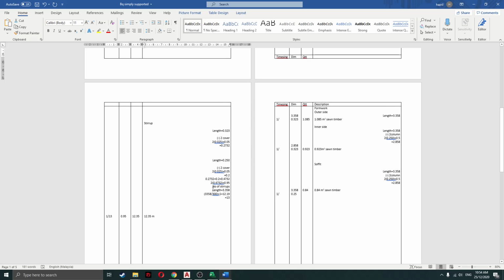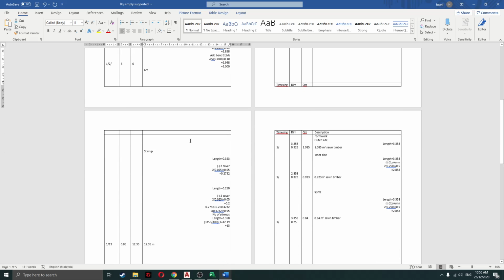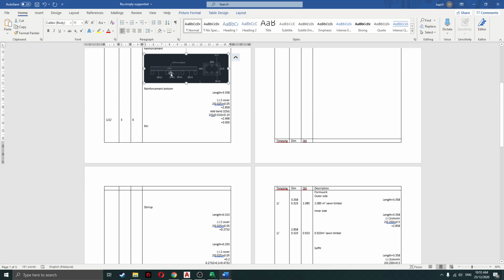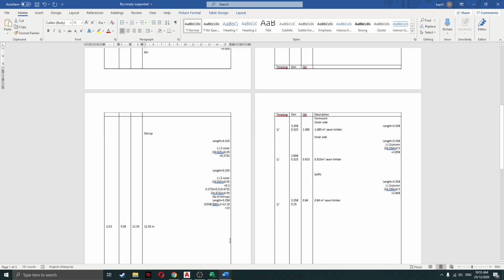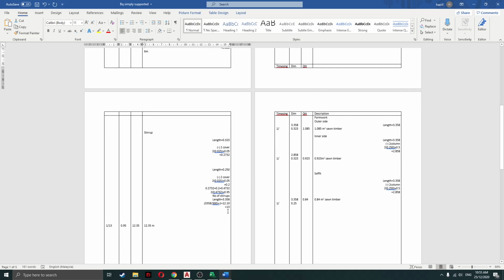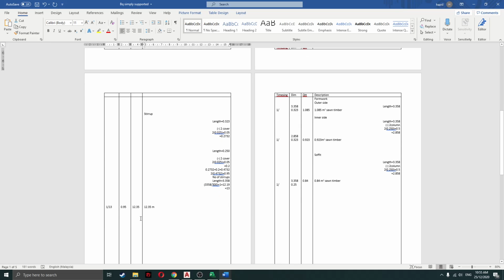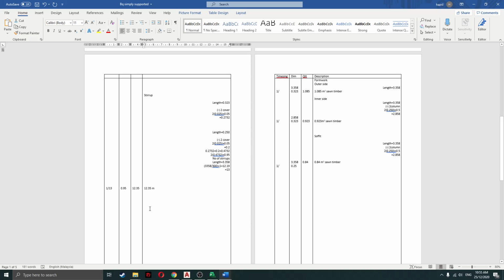Then we need to find the number of stirrup, the total length over the diameter and the spacing. I get 12.19. So I go for 13. Then 13 times the 0.95, the total, and then I get 12.35 meter.